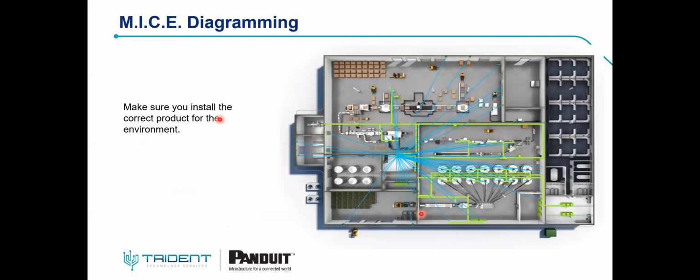As we said, the MICE standard is used to rate the environment. We are not talking about the product now. You are rating your environment. Each product used in the system design should be at least equal to or exceed the MICE evaluations for your space. So as you can see here in the drawing, there are two lines, the blue line and the green line. The blue line represents point-to-point cabling, or in another way, a single cable that can be used for all areas.